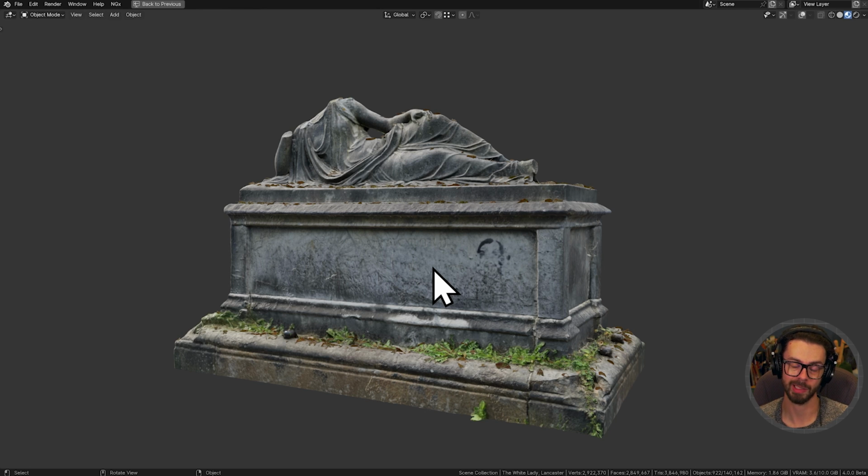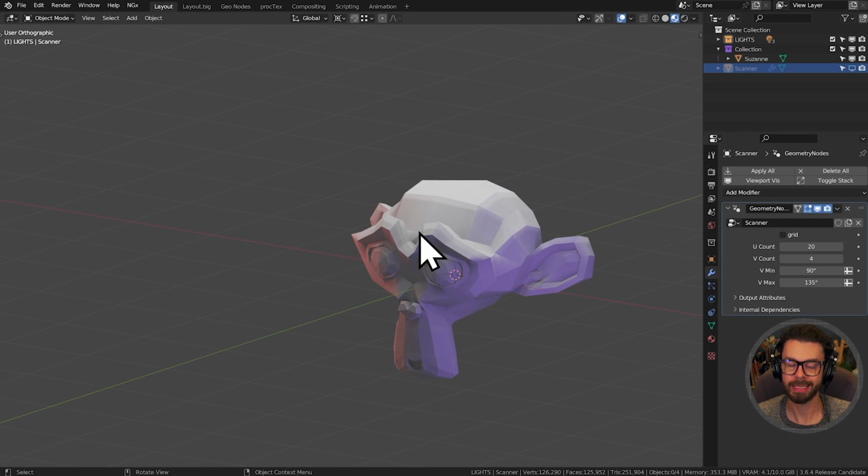output of that software. So the general idea of photoscanning is that you take a lot of pictures of an object, for example our Suzanne here, and by comparing the differences in specific features between two photos, we can identify, in theory, the three-dimensionality of it. So if you have 3 points and you have this sort of affine perspective change, then you can understand something about the surface and reconstruct the three-dimensionality.